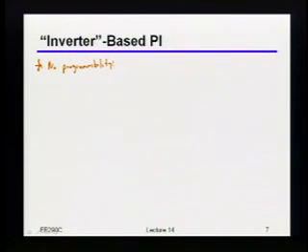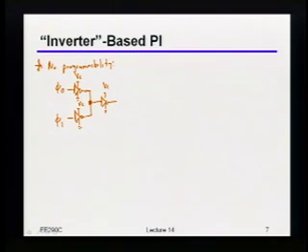And I'll already give you two phases of a clock. Just tie the outputs together. Yeah, exactly. Basically, I have a phi 0, I have a phi 1, I feed phi 0 into one inverter, I feed phi 1 into the other inverter, I tie their outputs together, and then, of course, I just buffer that out. Now, again, the only thing to be careful of is remember, I'm trying to reuse the PLL control voltage. So just to be clear, that means that the power supply of these inverters should also be set by that control voltage. Because remember, it's that control voltage that's setting the edge rates on those phase interpolators. Does this make sense to people?